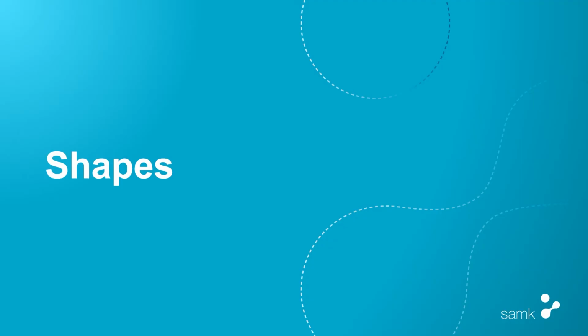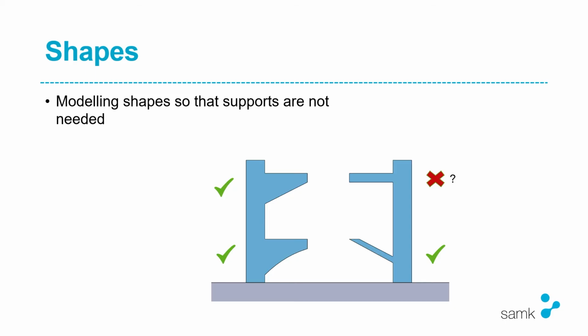What about the shapes when talking about 3D modeling? Modeling shapes so that supports won't be needed. If we make a pillar that has little bridges going outwards from the piece, and we use a fillet or a chamfer for that, it will come out nicely and it won't need any supports to get printed.